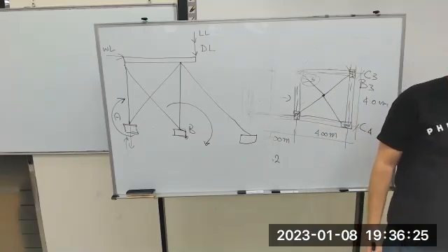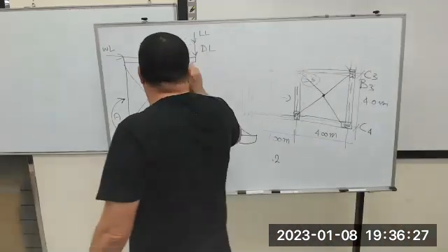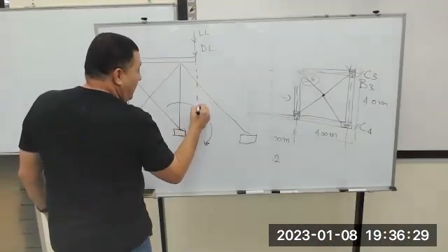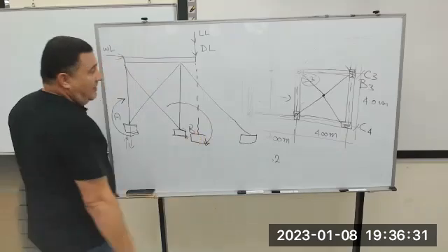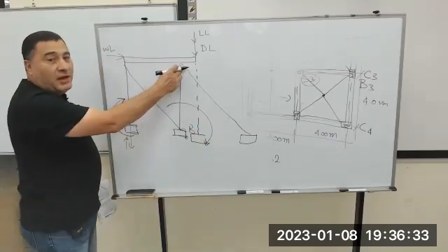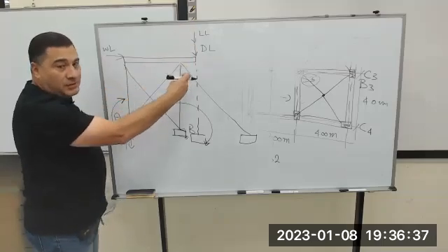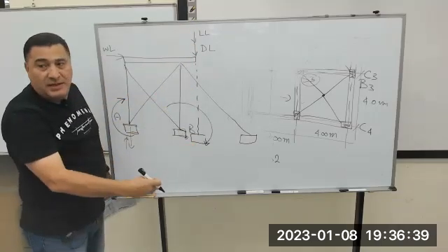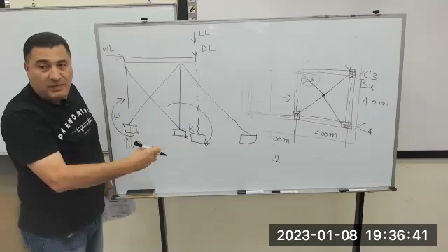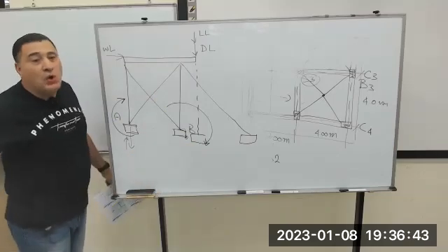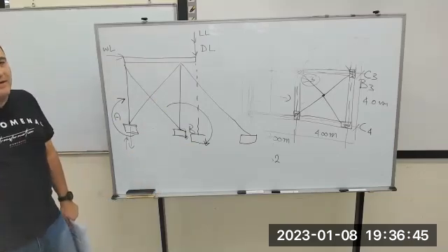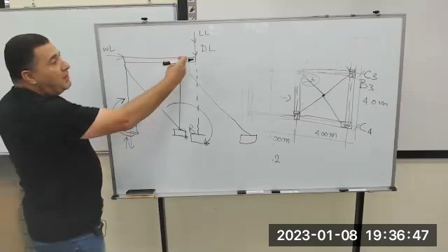Some joint condition. Make the system here, instead of having a cantilever. No, make the line of action of this load the same line of action as the center of the foundation. Then there is no moment in this direction.